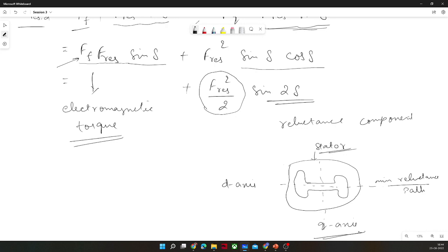Because if a stator MMF is rotating at synchronous speed, the rotor surface would always try to catch towards this origin, the least reluctance path. So that is the property of reluctance, right? The machine or any path or any steel or any core would try to attain the minimum reluctance path. So that's the fundamental property of a reluctance machine. I hope you would have grasped it.